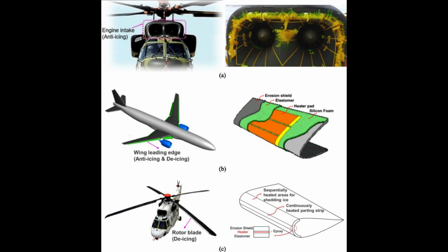Research is being done on lightweight icephobic, anti-icing materials or coatings. These materials placed in strategic areas could significantly reduce ice formation and improve performance. The pitot tube on a helicopter is very susceptible to ice and moisture buildup as well. To prevent this, they are usually equipped with a heating system that uses an electrical element to heat the tube.